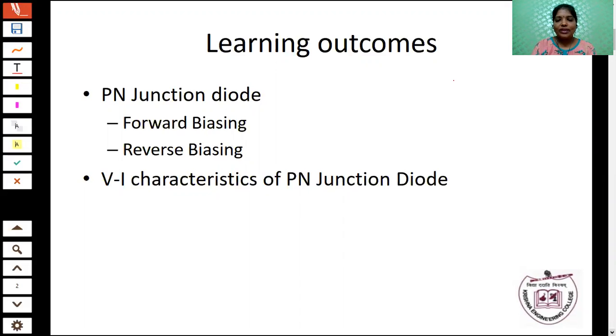In the N-type semiconductor material, the majority carrier is the electron and the minority carrier is the hole. In the N-type semiconductor material, we use pentavalent impurities added to the pure form of the semiconductor. What is the meaning of pentavalent? Pentavalent means the atom has 5 valence electrons in the outermost shell. So in the N-type semiconductor material, the majority carrier is an electron.